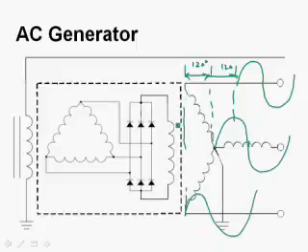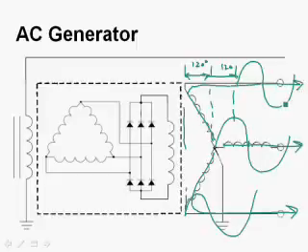And you're going, wow, Mr. Johnson, I remember that inductive reactance and capacitive reactance. If the volts and the amps are out of phase, it's going to mess things up. And you would be absolutely correct. But these three alternating current outputs coming from these three output windings are kept in separate wires, separate bus bars. So we never have this 120 degrees being out of phase, so we don't have to worry about XC and XL between the different phases.